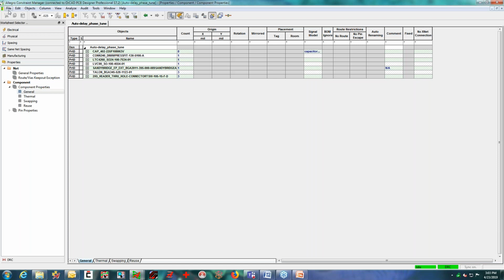It won't prevent you from doing it, but you might light up the design with a bunch of DRCs. And if you're okay with that, you could also waive them so that you get them out of the main DRC list, because the whole purpose in waiving things is